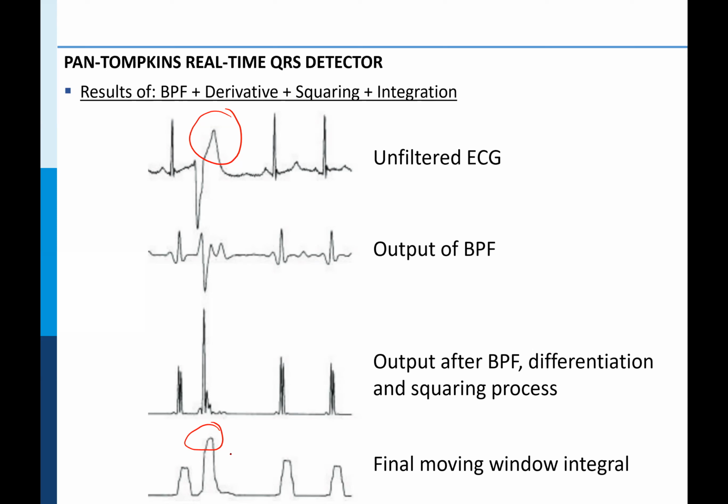But you could apply this thresholding scheme that I just mentioned and use some logic to basically tell that it's quite impossible from the heart mechanism that there are two peaks pretty close to each other. It's quite impossible in a normal heartbeat. So you could turn around the output of this moving average filter and use suitable logic to indicate there is something wrong with the ECG. There's an abnormality happening in the ECG.